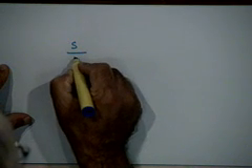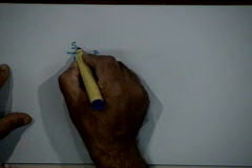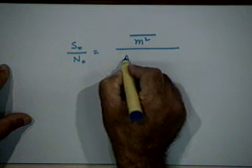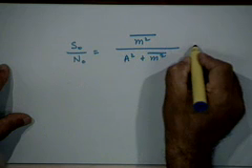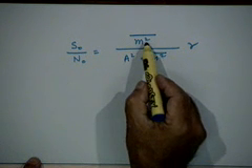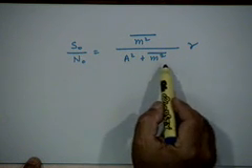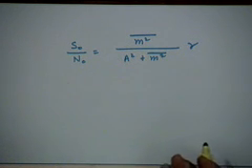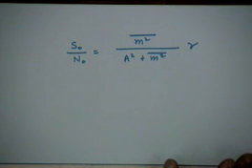in this particular case the output SNR was given by this kind of an expression, right, where this is the average message power, this is the carrier amplitude, and this of course is worse than what you get when you use DSBSC.